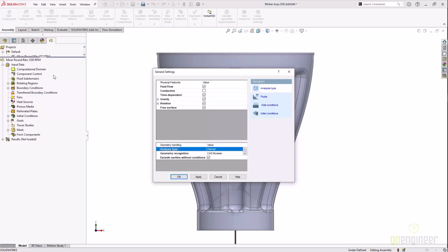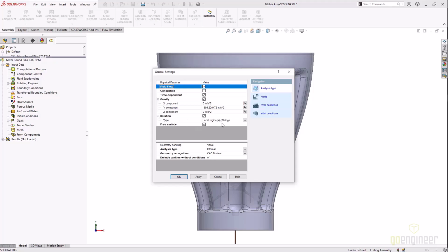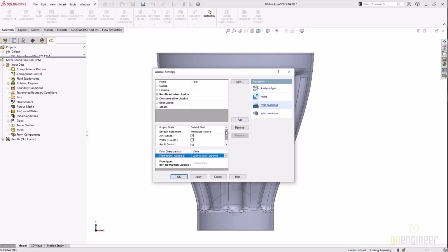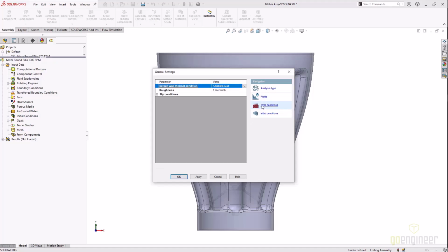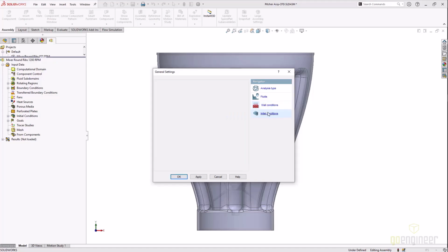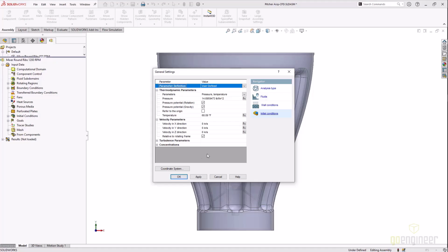So we are going to be spinning. We're going to be using a sliding mesh to rotate the mixing blade. We're using gravity pulling down in the negative y, and we're using something called free surface. And what that is, we have air sitting on top of the smoothie mixture. In this case, I actually use applesauce to represent the fluid in the bottom of the container. Now, a couple things in there. I actually have 2 layers of applesauce in the model, and the reason for that is I have 2 different temperatures of that fluid in the model.